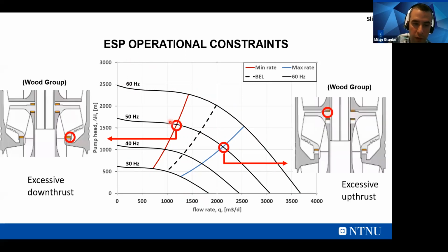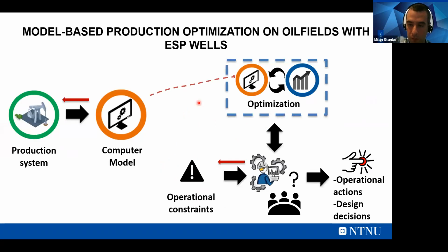Or if you have floating impellers that are able to stroke up and down, you might have too much wear that causes early pump failure. So it typically looks like this trapezoidal shape. And if you have a different viscosity, of course this is going to change. We're going to see that later.